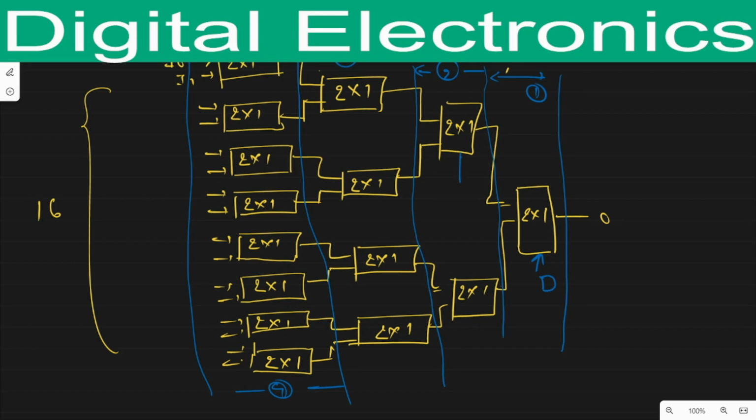Now the second stage multiplexers will contain the neighbor of LSB, that means they will contain the selection line C. These multiplexers contain selection line B. These all will contain selection line B. And at last the first stage ones contain selection line A. All of them contain selection line A. Because the selection line is common, that's why we will take the inputs as I2, I3, I4, I5 till I15.